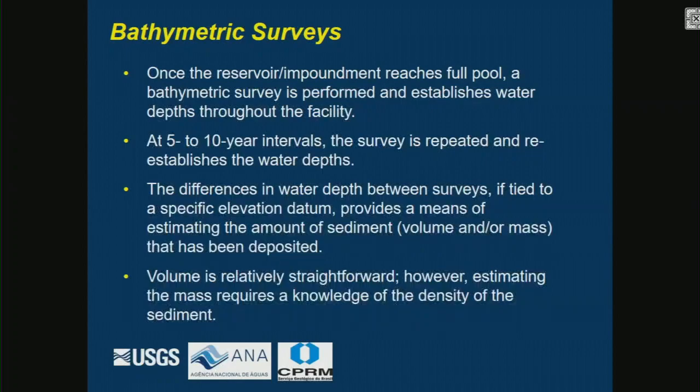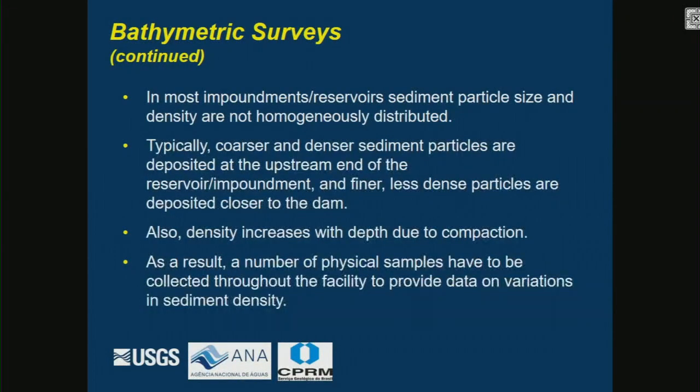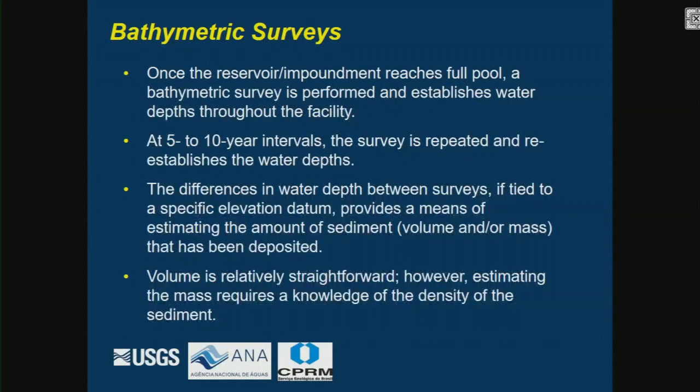So on a 5 to 10 year interval, you might want to do something like a bathymetric survey or some of these other techniques. And getting the volume is fairly straightforward. But getting the mass is another story, because you need to know the density of the sediments.